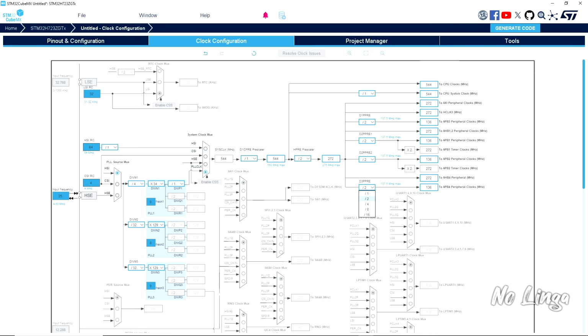Our microcontroller can go up to 550 megahertz, and this time I just want to go ahead and configure it for the max right now. Here I will go ahead and enter 550 megahertz and then hit enter, and it will start the configuration. And the clock did make some changes. I'm still going to have to go ahead and make some correction for my own satisfaction based on what we want. But at least for now, it has it configured to this point.